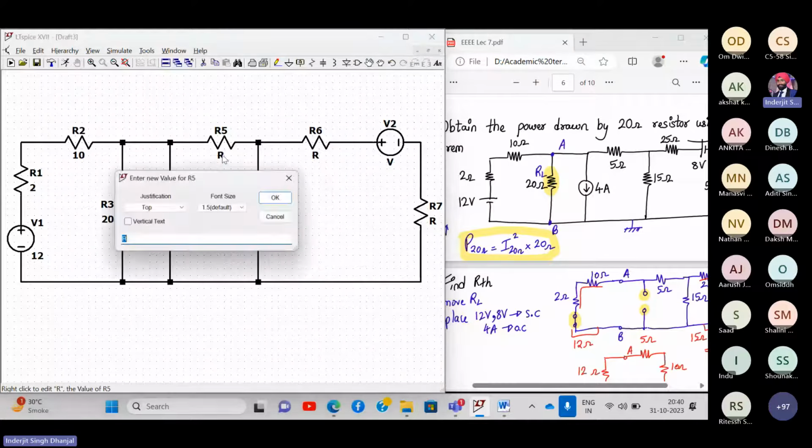Did you understand? We need to find RTH, VTH, then make the Thevenin's equivalent circuit and then find the current. Are you all understanding what I'm telling you? Yes, sir. So we have to make 3 circuits for the Thevenin question. Exactly, because if I find it directly, then I'm not using Thevenin's theorem. Directly, you can find to cross check your answer. Is that fine?